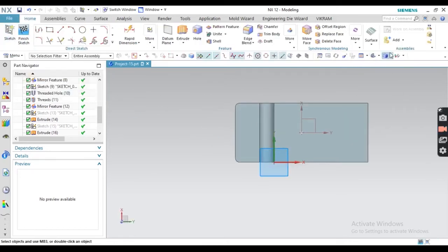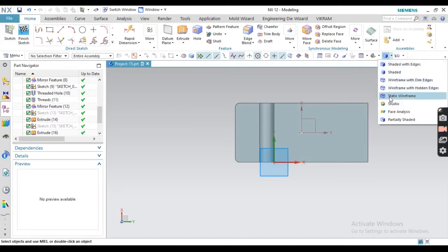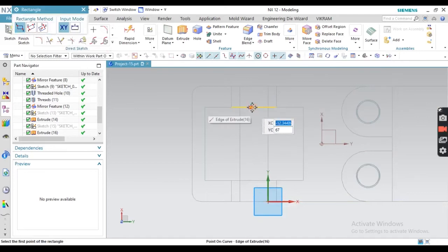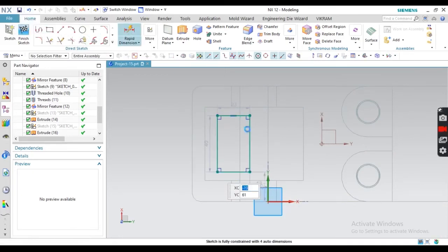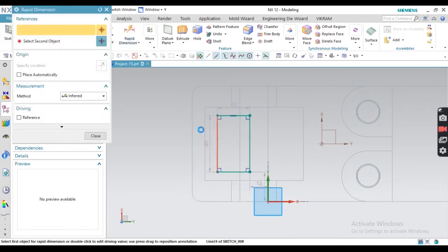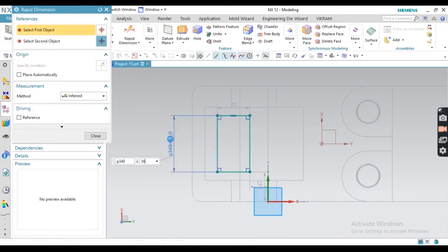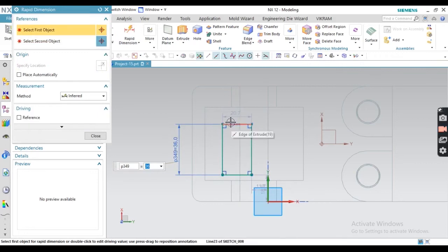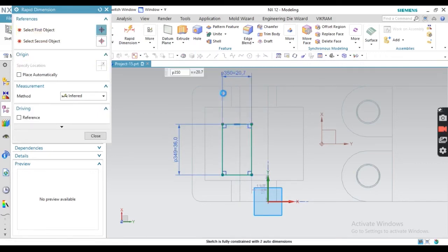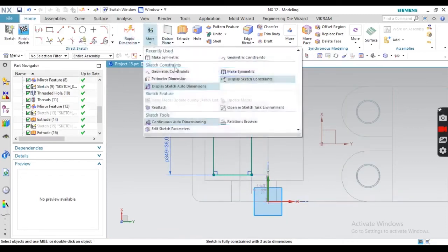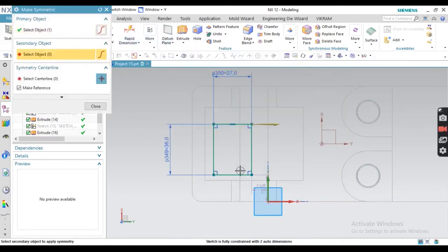So I'm going to do a revolve cut here. Go for static wireframe, and in the bottom first create a center line. I want to cut with the revolve option. Just see what I'm doing here. I'm creating a rectangle first, but actually a semi profile. What profile we have to cut, it's the semi profile only. Sorry, the semi profile we are going to cut here.